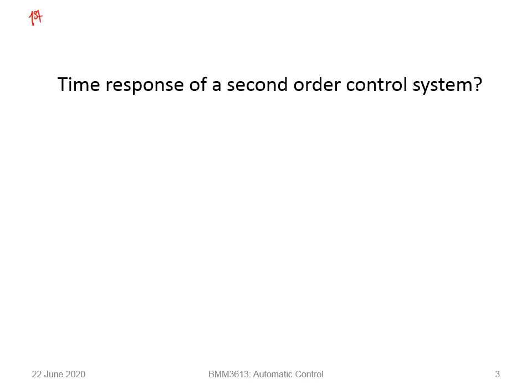In first order time response, all the time responses look alike. If you remember, when we studied the performance criteria, the time response looked like this, right? When we have the general form of the transfer function G(S) as A over S plus A, and we find the pole equals minus A, as a function of the value of A, the form of this time response could change.